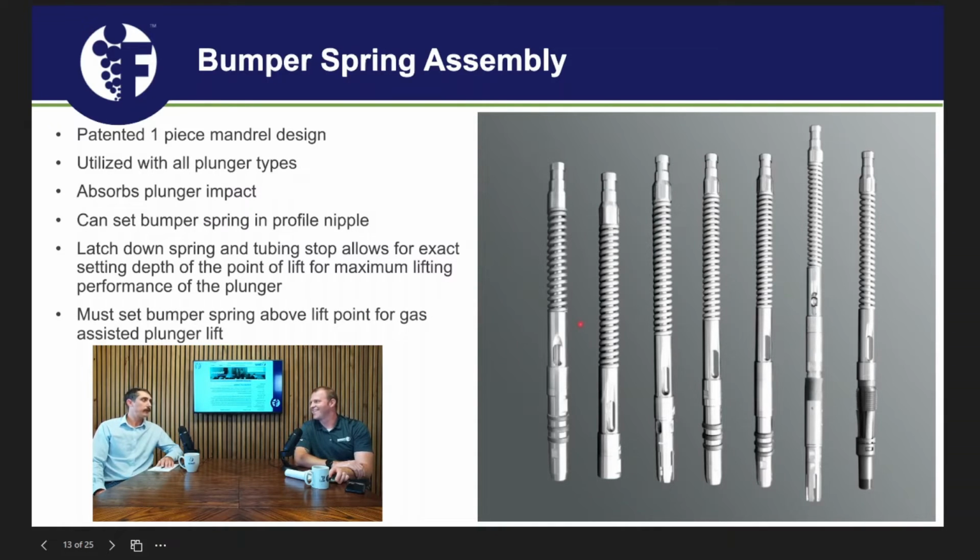I've got mixed feelings. It's not a good idea if we're doing it for the first time. This is Plunger 101. I always push for success on the first run, and we'll talk about the installation here in a bit. If your field guys are very experienced and they know what to look for, you can drop it from the surface. If it doesn't seat, you'll probably know it. It'll come back, and then you know what to do. Really, it's ill-advised; run slick line, but I've seen it done a lot. Okay, and I have too. Good question on that.